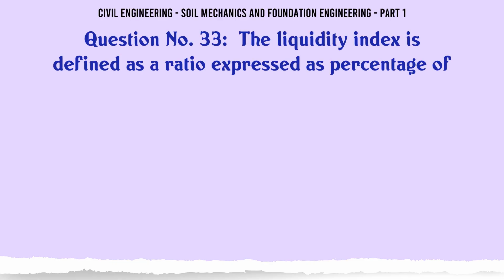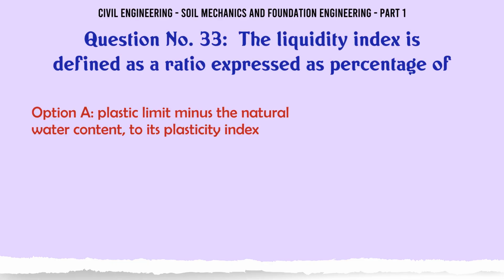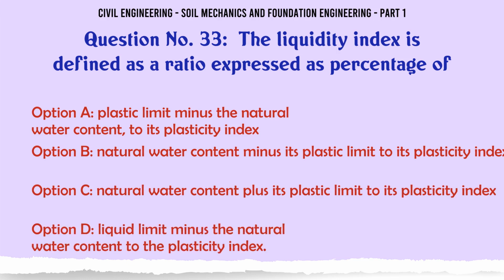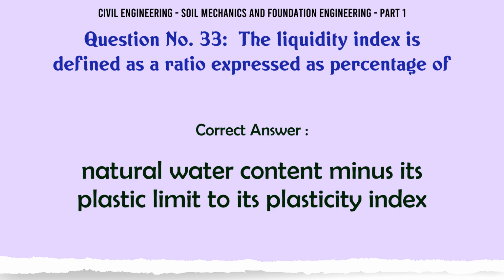The liquidity index is defined as a ratio expressed as percentage of A. Plastic limit minus the natural water content to its plasticity index, B. Natural water content minus its plastic limit to its plasticity index, C. Natural water content plus its plastic limit to its plasticity index, D. Liquid limit minus the natural water content to the plasticity index. The correct answer is natural water content minus its plastic limit to its plasticity index.